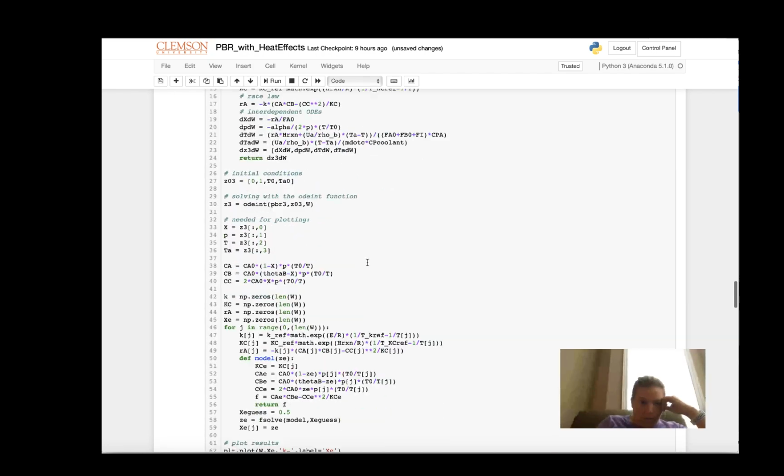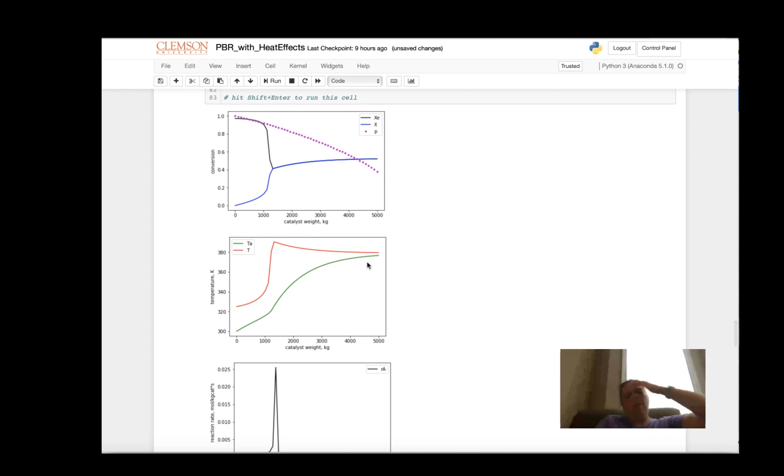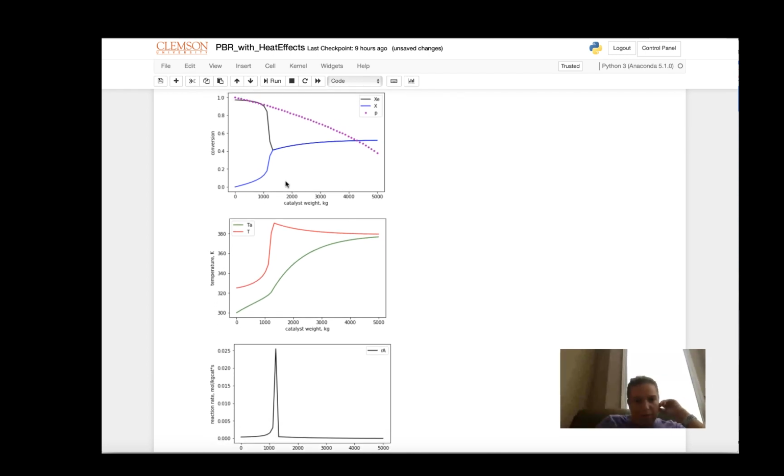All right, co-current. So again, here are my plots for X. So again, my rate increases pretty rapidly. I get up to about 400 degrees. That's where my reverse reaction comes into play. But now I have a heat exchanger again. So the heat exchanger works to reduce the temperature, and because of that, the conversion is allowed to keep increasing over the course of the reactor, albeit somewhat gradually. So you see here the equilibrium conversion meets with the actual conversion, and then they track each other for the remainder of the reactor.